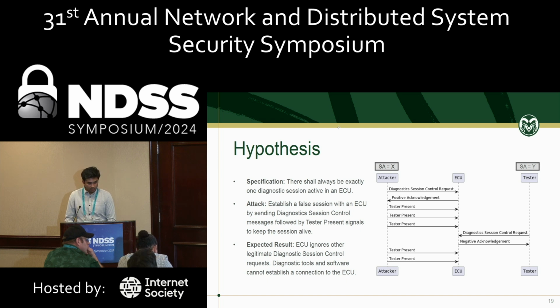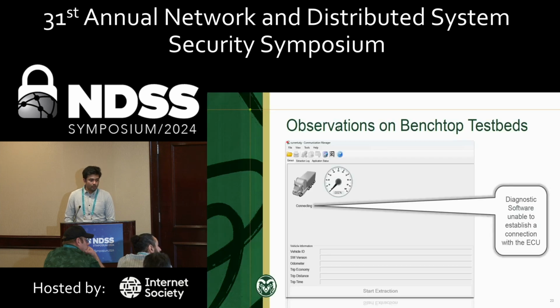We did try it out, with the attacker creating a diagnostic session and sending tester present messages to keep the session alive, while at the same time the tester tried to establish a valid diagnostic session. We did observe that the diagnostic software during the attack was not able to establish a session. As you can see in the screenshot, the diagnostic software just said connecting and could never connect to the actual ECU when the session was being hogged by an attacker.